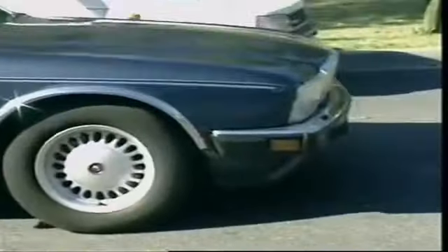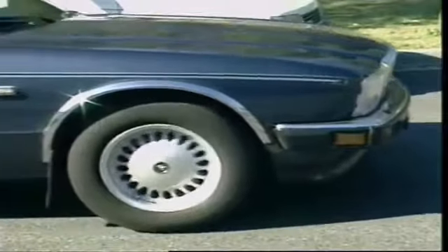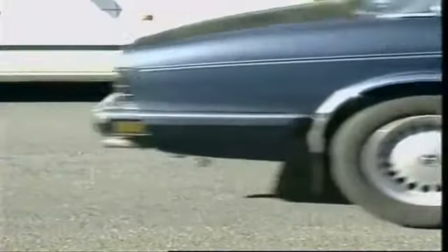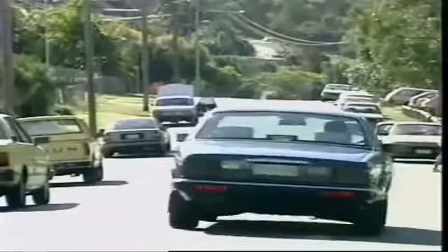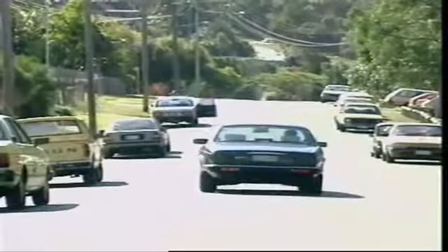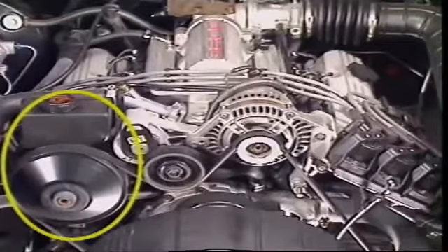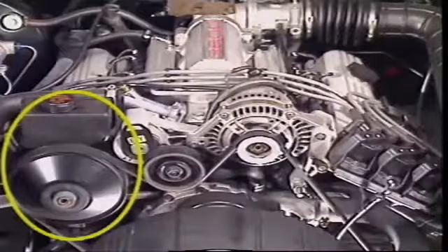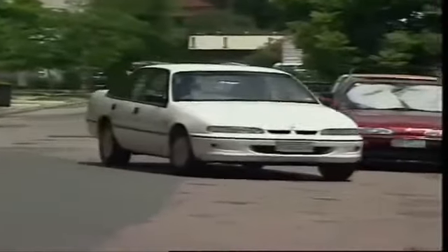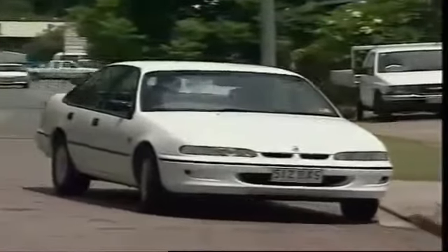With heavier vehicles, increased use of front-wheel drive and wider low-profile tyres, more steering effort is needed, so power steering is used. An engine-driven hydraulic pump provides pressure that helps the driver steer the vehicle. The power steering system is designed so that the vehicle can still be controlled, even if the engine or the power steering system fails.